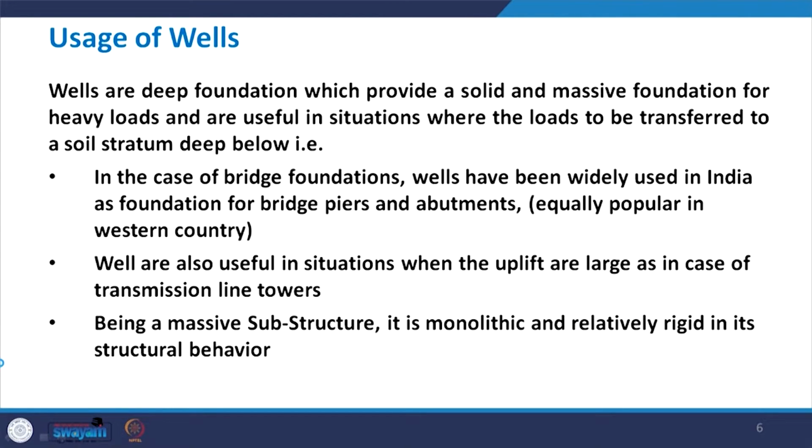So, two issues with the well: one is that the load to be transferred is heavy, and it needs to be transferred to a deep stratum. The difference with the pile foundation is that wells are basically large diameter piles. In many other ways they are common, both pile foundations and well foundations being deep foundations.